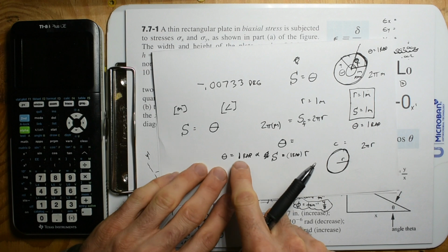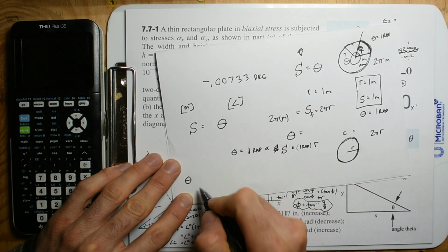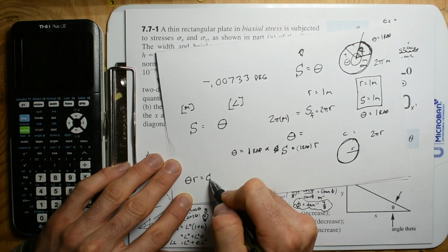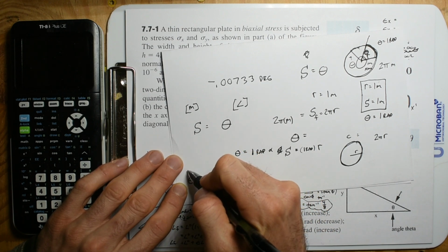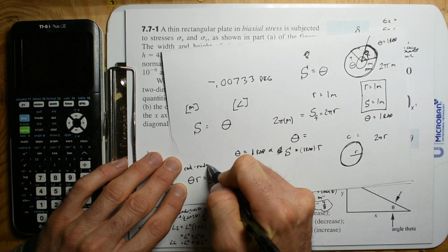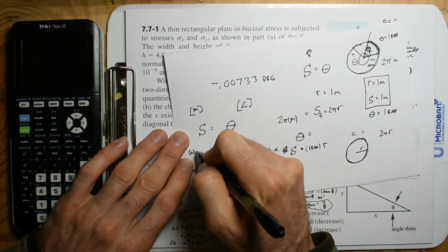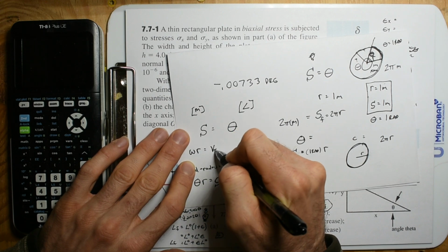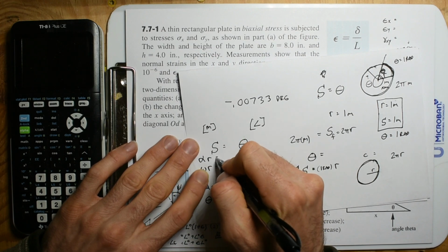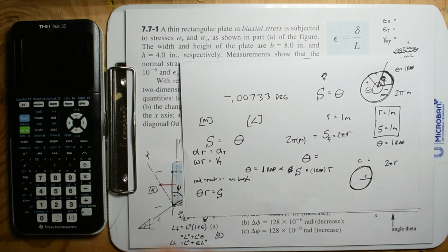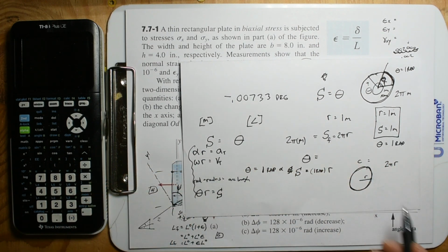And that is the reason that I just have the axiom that radians are bizarre, and so radians times radius is arc length. When you take radians and multiply it by a radius, you get something normal. So radians times radius is arc length. And you can do this with omega. Radians per second times radius is tangential velocity. Angular acceleration, radians per second squared times radius is something normal. That's a tangential acceleration. So those are the three that you can use. The radians times radius is something normal approach.